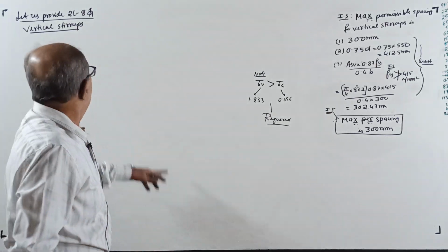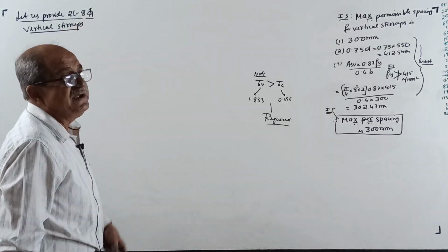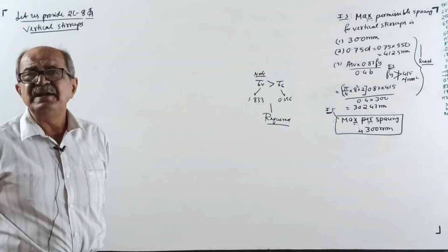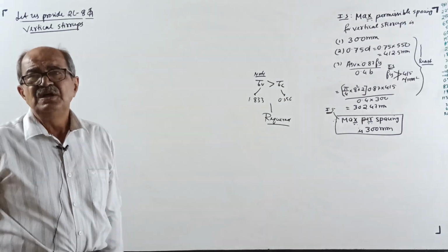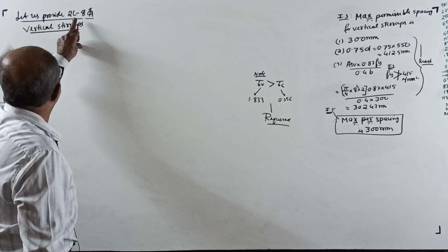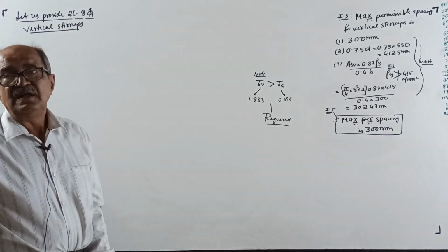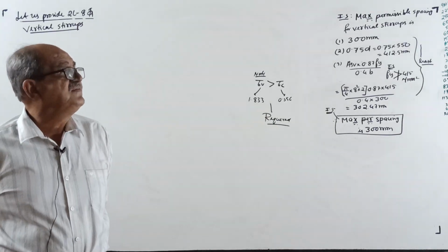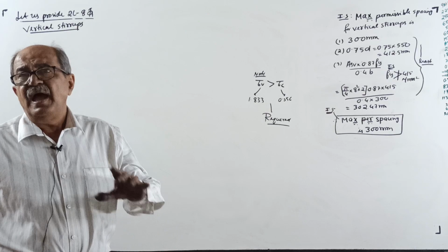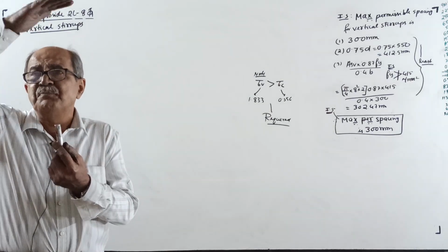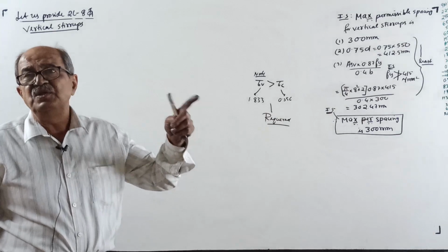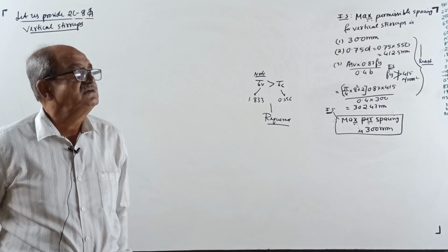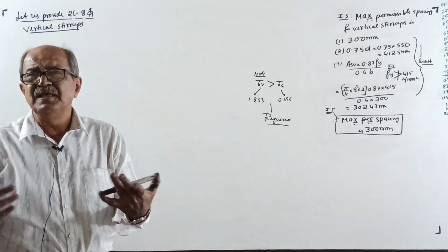Then what you can do is either increase the diameter, instead of 8-tor, slightly more. Usually 8-tor, rare case 10-tor, worst case 12-tor. And still very heavy force, instead of 2 legs, you can go to 4 legs. There is one more option. What shear force you considered, if it is at the face of support and if the support reaction gives compression to the beam, then you can move by distance d and consider a little lesser design shear force. That all comes in the class.